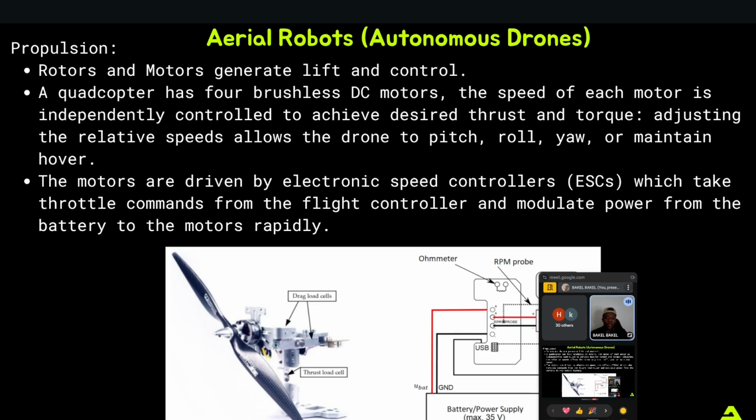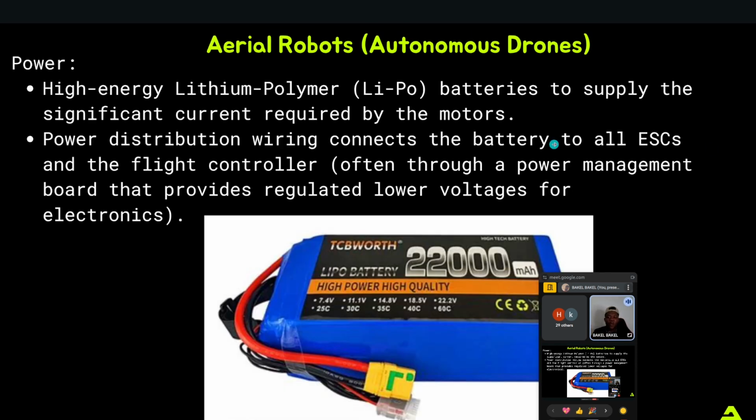For the propeller, you give speed, and that speed has to be translated into power or current that is sent directly to the motor. That's what the ESC does. It allows us to write high level code rather than manually writing the code that turns the propeller. That's for propulsion.